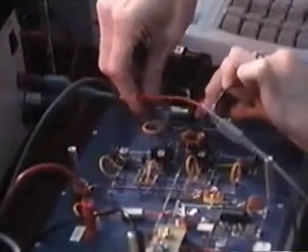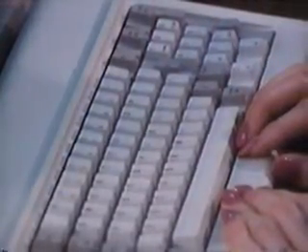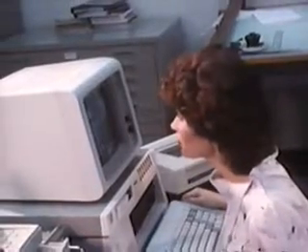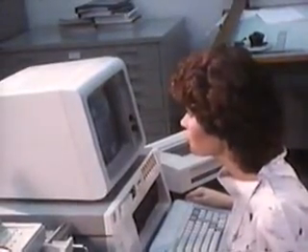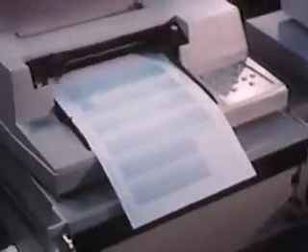She hooks her system up to the modulator she is going to test and hits J, which turns on her stimulus, the AC test signal. She verifies the test connection to her circuit and hits J again to start the plot. Note that the title, date, and time were automatically annotated by the plotter. The red graph indicates gain in decibels. The blue, phase shift in degrees.